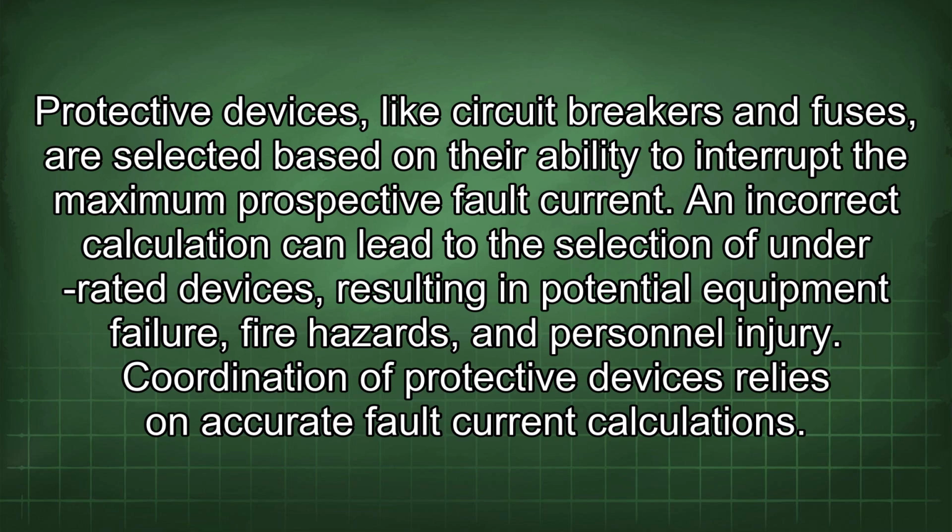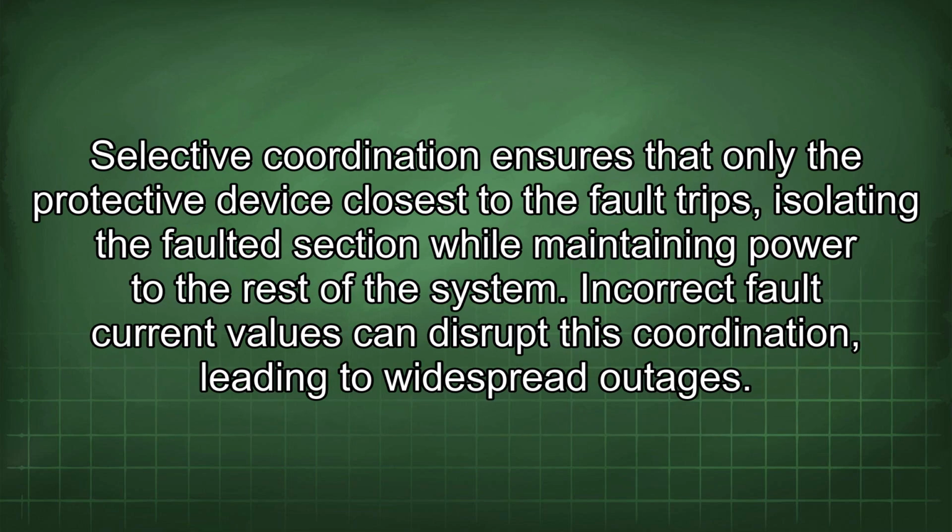Coordination of protective devices relies on accurate fault current calculations. Selective coordination ensures that only the protective device closest to the fault trips, isolating the faulted section while maintaining power to the rest of the system.